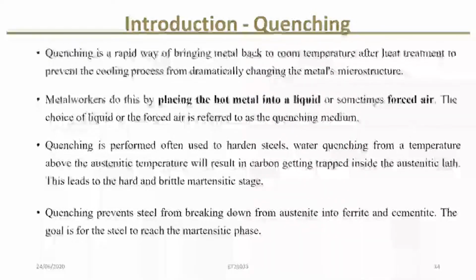Salts can be tuned, and polymer quenchant sits between water and oil. The art is picking a medium that's fast enough to reach martensite, but not so fast that you crack or distort the part. As an example, a thin knife blade might handle an oil quench, while a thick die block might prefer a polymer or interrupted quench to limit the thermal gradient.